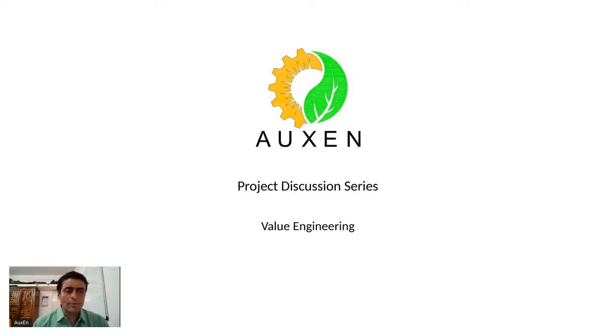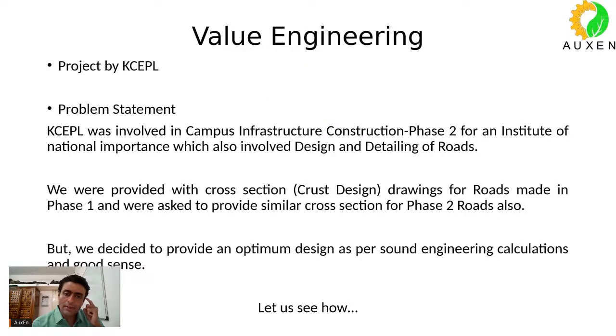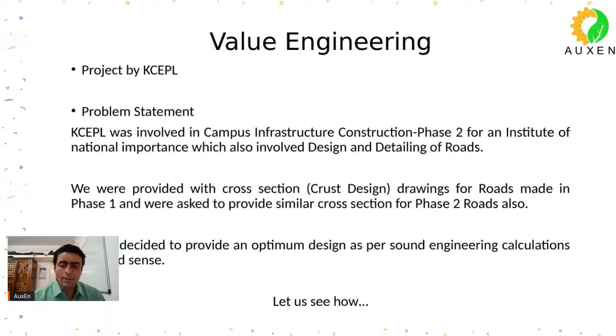When we write, let's say, 8 dia stirrup at 150, what you write on paper with a pen gets executed on site. So you should think whether what you are providing is required, is it optimum, whether you can economize any further. That is a very important question you should always ask yourself, and it is a big responsibility that we as structural engineers have.